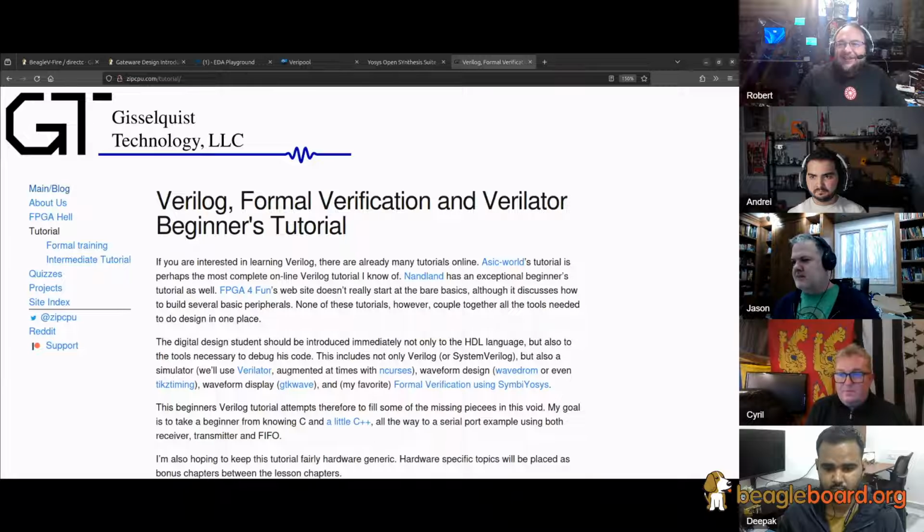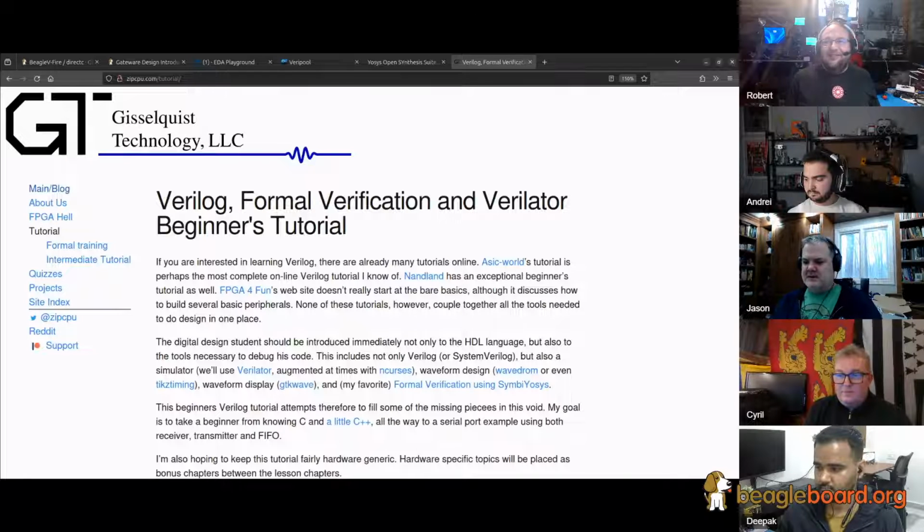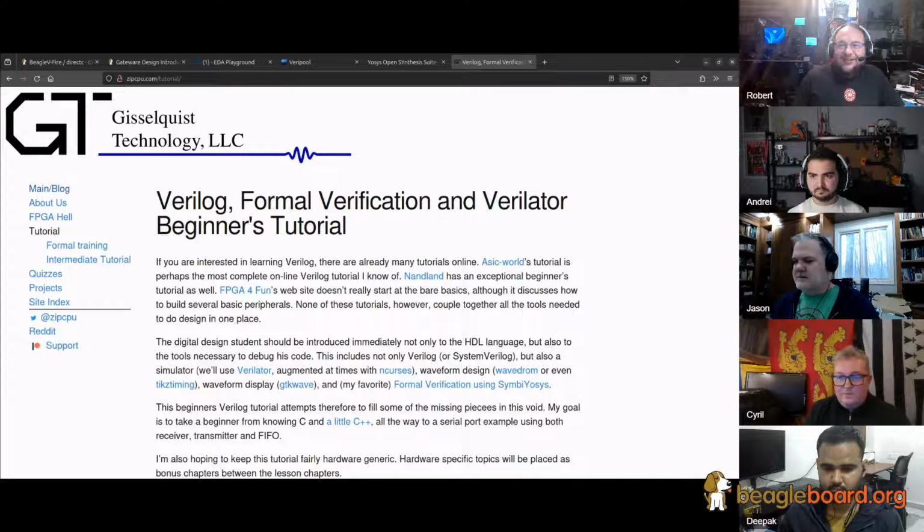And we have a lot of that with stop mode debug, with JTAG, but when we're typically doing Linux debug, we're looking at runtime debuggers like GDB, things that do software trap based debugging, right? So you replace the instructions with things to go into the software, and then you go and look at the registers. I think it gets interesting when you've got the ability to instantiate a CPU that you're not limited to just JTAG scan to get access to all the internals.